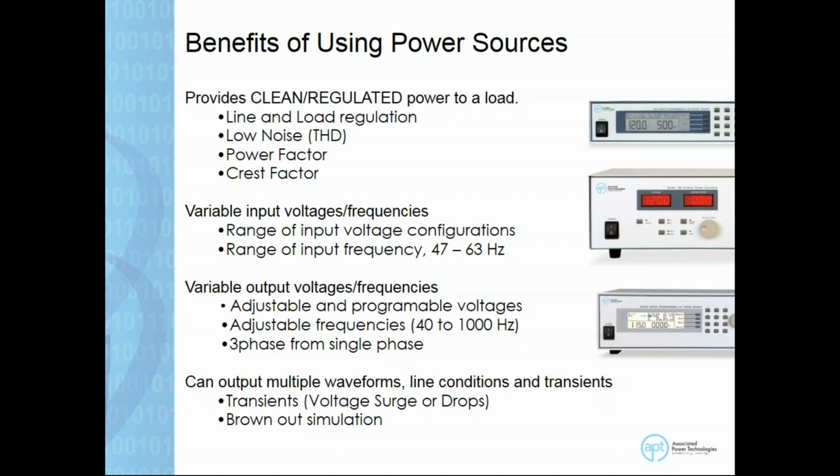Now, we also run into a situation where a customer may have a product they're being tested for overseas. So they need to apply 230 volts and nothing around them has 230 volts. In this case, you're able to take a power supply and deliver the proper voltages you need for proper testing. You could also convert single phase or split phase power into three-phase power. So if you had a requirement for testing a three-phase product, you either have to call an electrician to do a voltage drop for three-phase, or you could buy power supplies that could output three-phase while only taking in single-phase power.